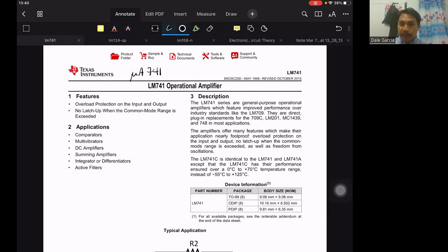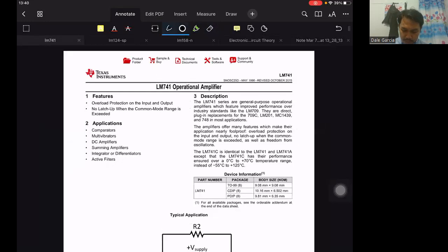It doesn't matter which manufacturer, because the circuit inside the integrated circuit that makes up the op-amp is standard. If you go to a store or see parts like this, 741, again, it doesn't matter who the manufacturer is. You can just say you want the 741 there. So, you want a general purpose op-amp.